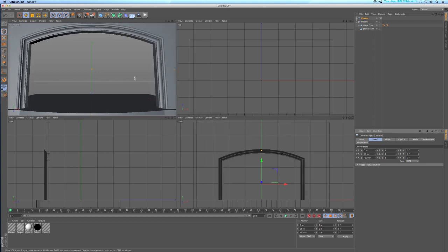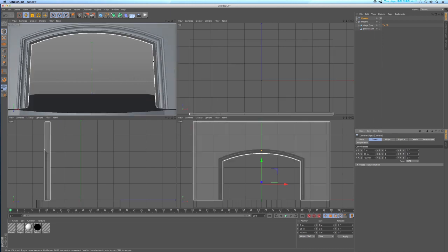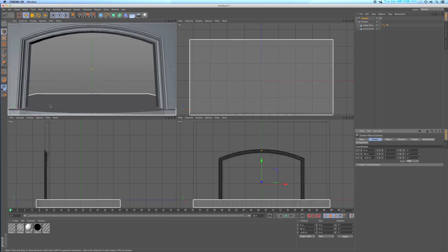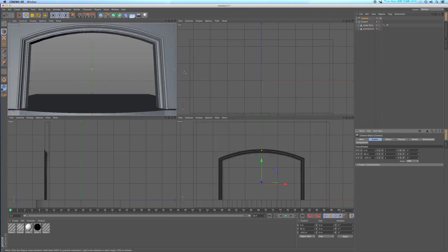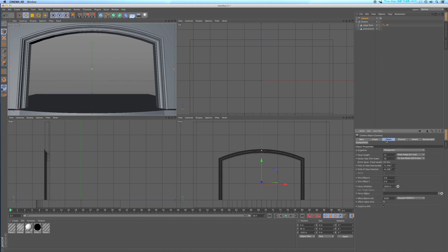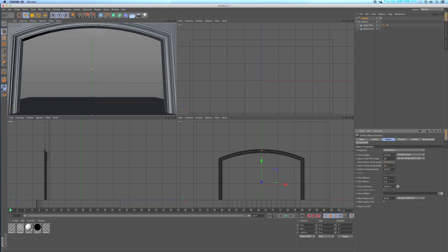Now one thing, and this is very much a personal preference, you can set it however you want, but to me this proscenium is tipping in so much, it is distorted a little bit too much for my taste in the perspective. So I'm going to go back to Object, and here in the field of view, instead of 70, I'm going to change this to maybe 65 might work, which zooms me back in, so I need to go back to my Z and back the camera out.